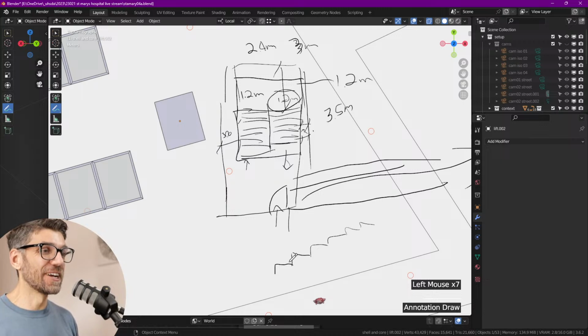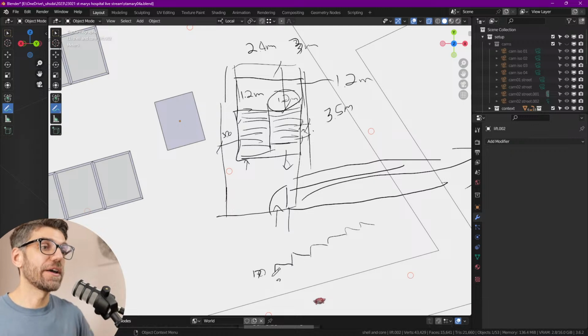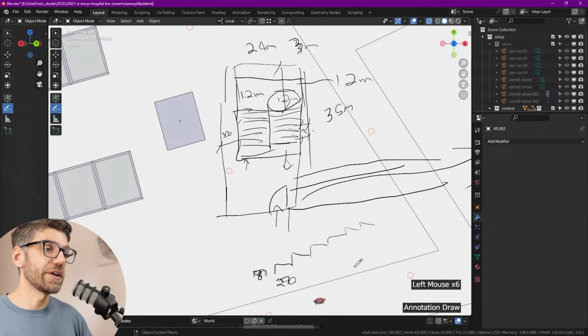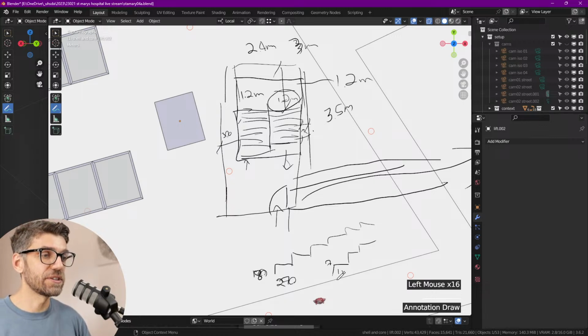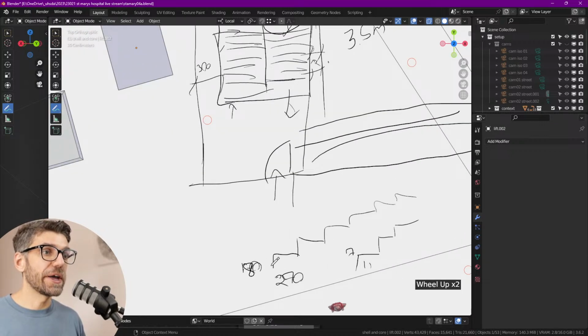What is the word that I'm looking for? It gets very technical, right? So the minimum stairs in Europe metric is 180 by 270. Or if you're in the US, it's 7 by 11. Some things I really prefer in the US system because they make it so much easier. Like 7 by 11, that's something I know from college and I'll always remember it because it's very straightforward. But because we're doing this project in metric, since it's in London, we're going to use the metric numbers.